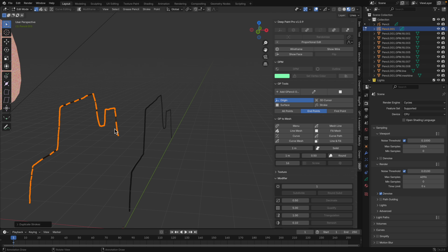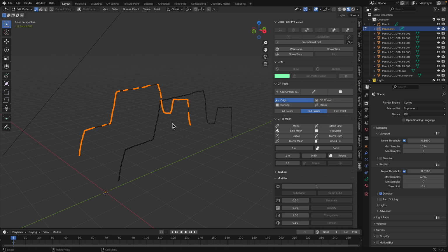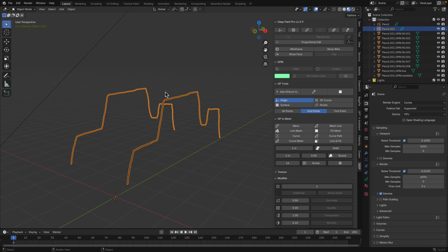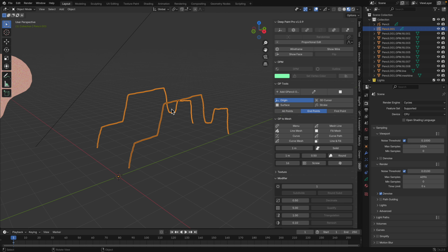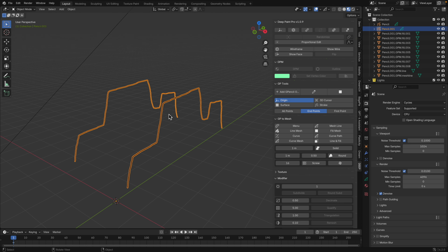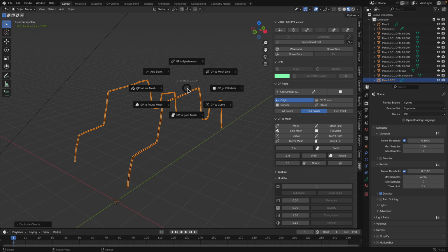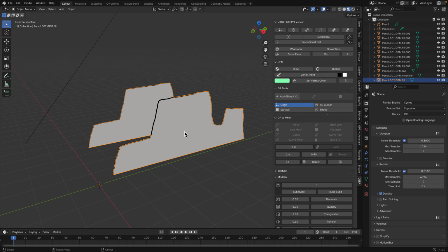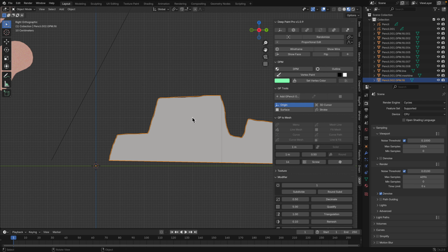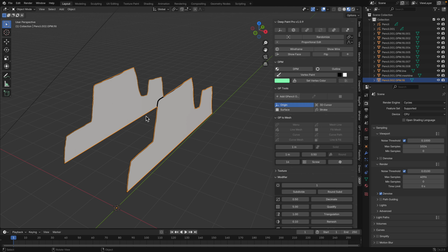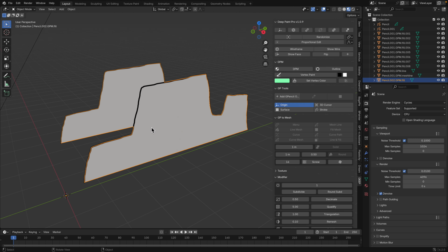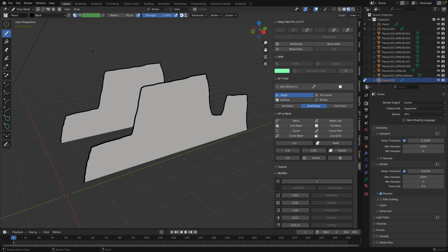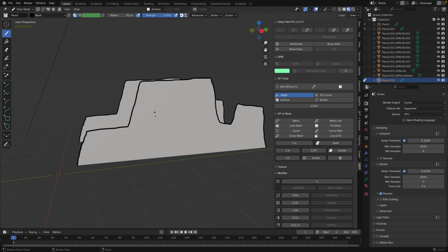You can always duplicate this, and then you can turn it into shapes very quickly because it's in Blender. So if I duplicate this and then E, convert it into fill mesh, yeah, it's going to fill that. I think Feather 3D doesn't have that, but with Blender you can, and you can do extrusion, things like that. On top of this, if you create a grease pencil, once again, you can draw the stroke on the surface.